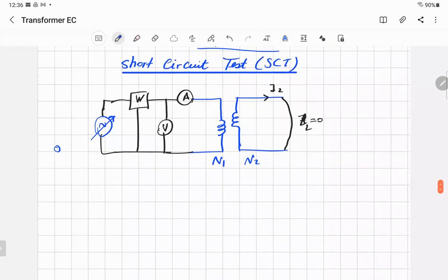First, very important, the voltage is increasing gradually. Start from 0. Always start from 0. From 0 voltage. And you start to increase the voltage while watching the ammeter in the lab. And try to get closer to the rated value of the current on the side. And then you stop the voltage.